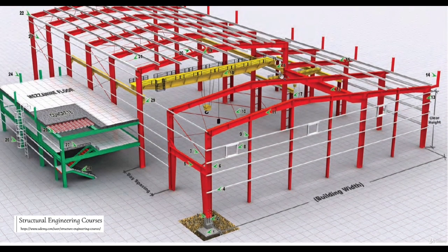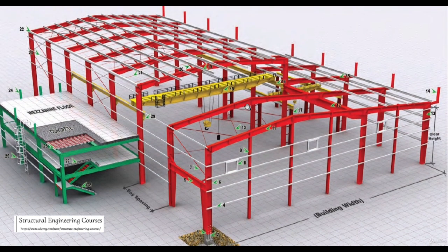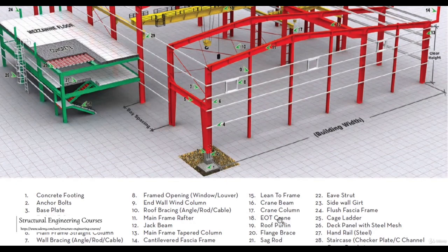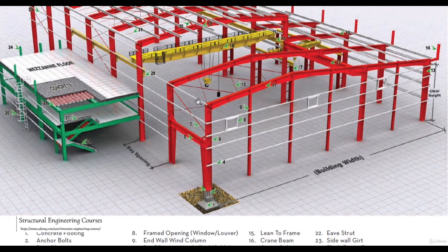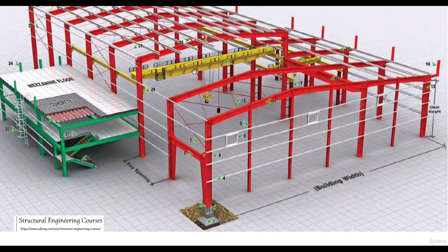Now this is also a very interesting concept. If you have seen pictures of warehouses, or you might have been to some warehouse also, you might have seen these types of gantries or EOTs here. It is called an EOT crane, that is, electrically operated traveler crane. The lifting capacity of these EOT cranes may vary from 2 ton to either 30 ton or 40 ton, also on the higher side. So what exactly we as a designer need to do is that we may need to support this EOT crane on these columns here also.